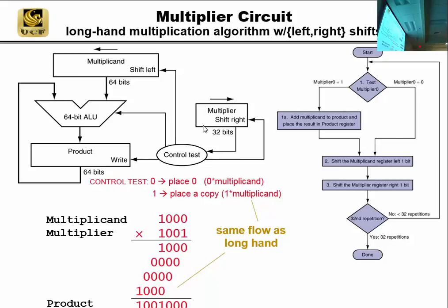So we have 64 bits, and starting with 32 bits is 0. So there's all the zeros here, and then 32 bits from the register. Which register? RS and RT. Where's the RD? Is the product. How many bits in the product? As we mentioned, it's 32 bits times 32 bits. We started with 32, and we had 32 zeros. So 32 bits times 32 bits, 64 bits.